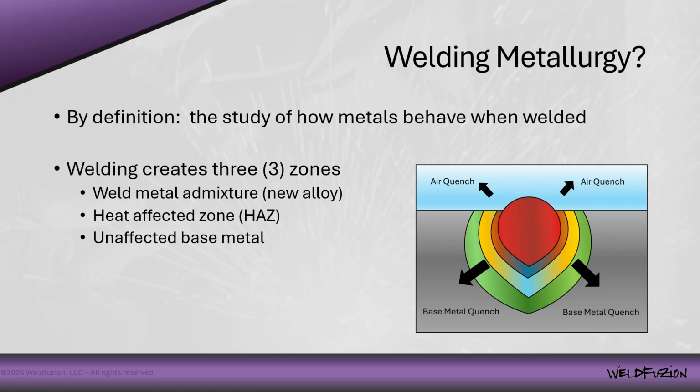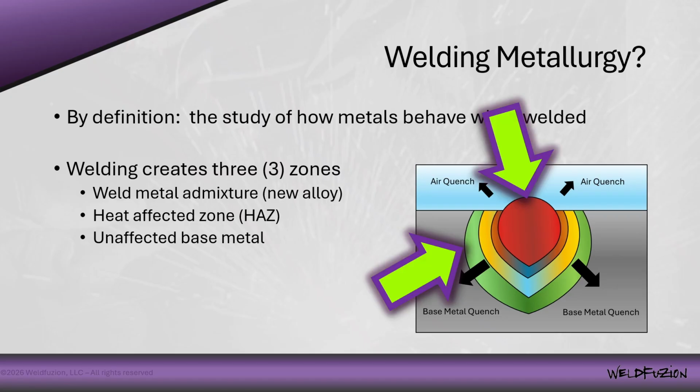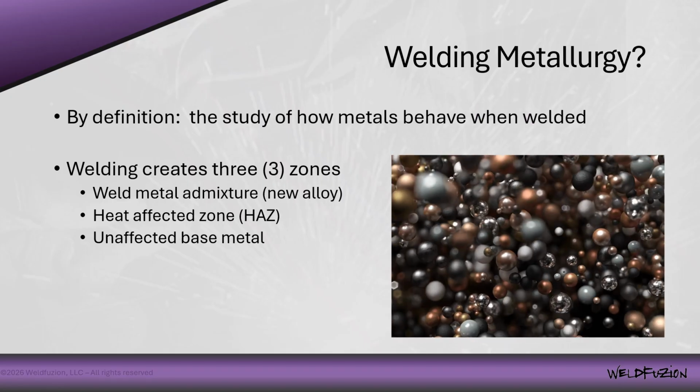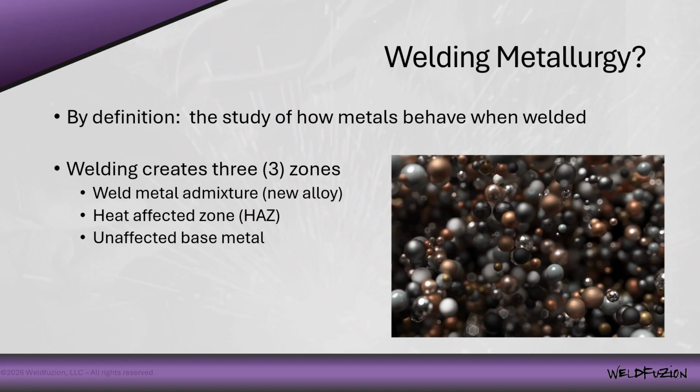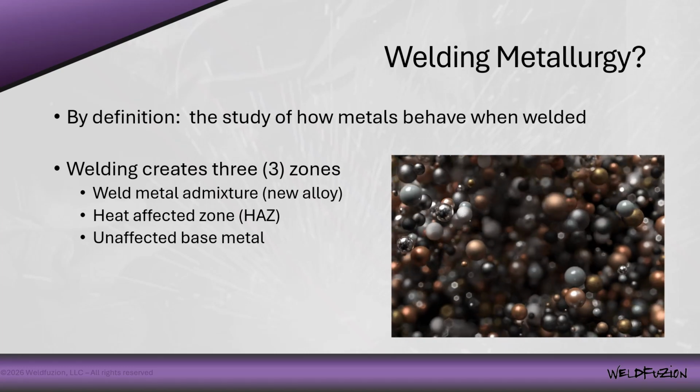So welding is most concerned with the melted admixture, that new alloy we created between the two parent metals and the filler metal, and the solidification rate, that generates a certain heat affected zone and the subsequent microstructure after welding due to phase transformation and recrystallization, or the movement of metal atoms in the element when it's heated or cooled.